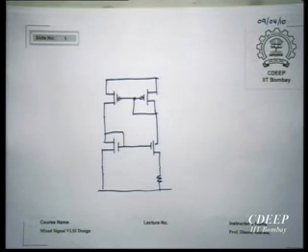Okay, which transistor should we make larger? Make up your mind. The one with the resistor should be larger, because it should pass the same amount of current with less voltage, because some voltage was eaten up by the resistor, right? So the larger transistor should be the one. So let's say that it's larger by a factor k. Okay, the geometry ratio, and this is what makes the circuit so much better. That is to say, the geometry ratio is 1:k. It is a ratiometric circuit, doesn't depend on the absolute value.